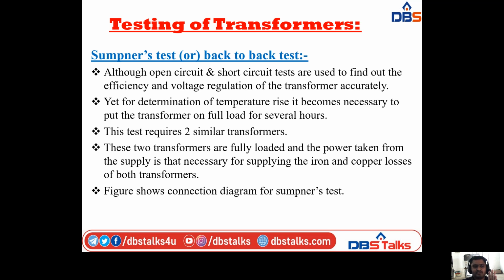So that means we have to apply the load in this test. This test requires two similar transformers. These two transformers are fully loaded, and the power taken from the supply is necessary for supplying the iron and copper losses of both transformers.